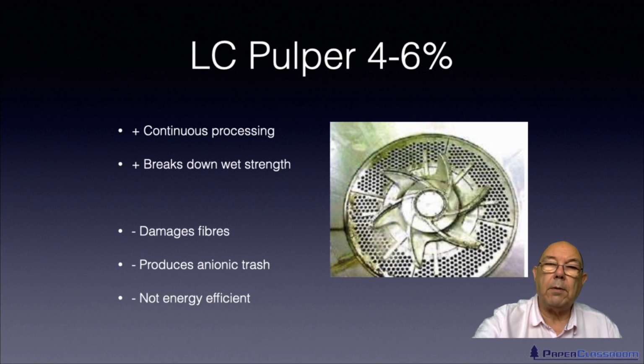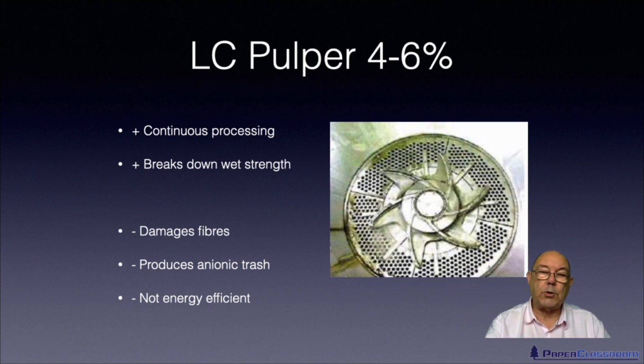If you take a fibre, like this, you throw it in there, then before it gets a chance to absorb water and to swell, it snaps. So you've now got two short fibres. So you're constantly reducing the average fibre length. And a little mantra I've been saying throughout these courses is the longer the fibre, the more the crossovers, the stronger the sheet. Therefore, damage to fibres, the shorter the fibres, the fewer the crossovers, the weaker the sheet.